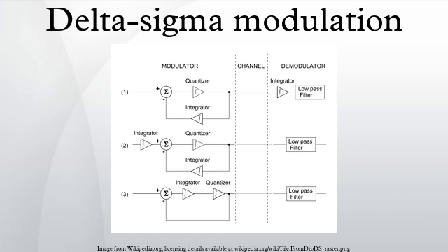maximum count. It is then possible for the impulse duration and the summing interval to be defined by the same clock with a suitable arrangement of logic and counters. This has the advantage that neither interval has to be defined with absolute precision, as only the ratio is important. Then to achieve overall accuracy it is only necessary that the amplitude of the impulse be accurately defined.